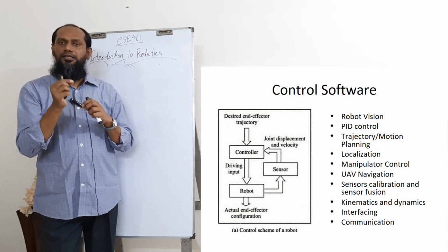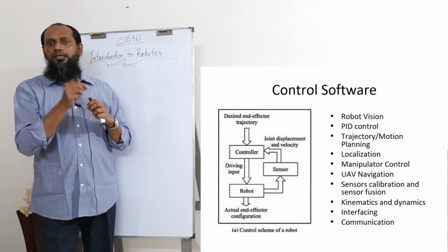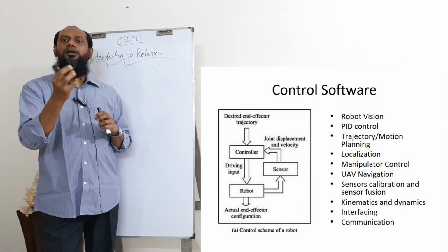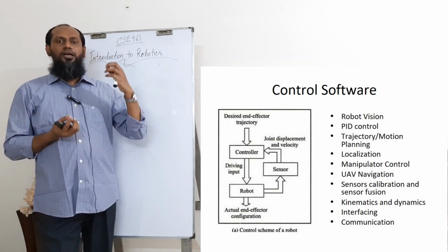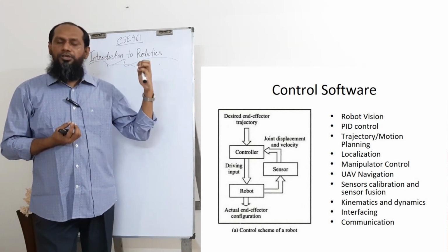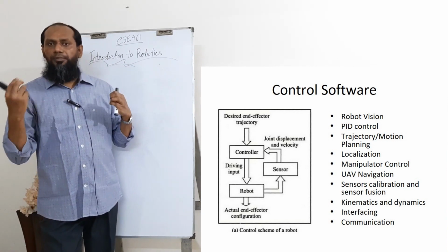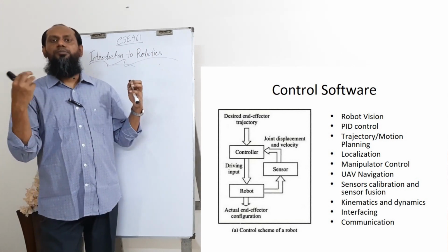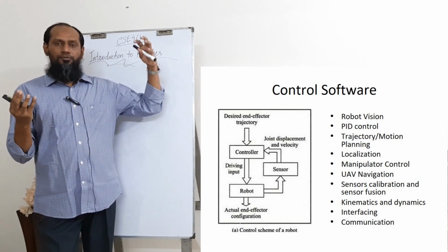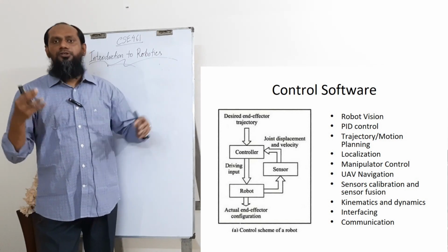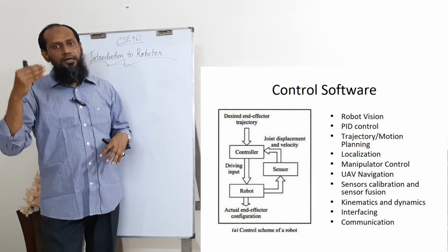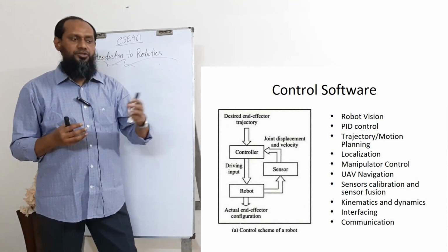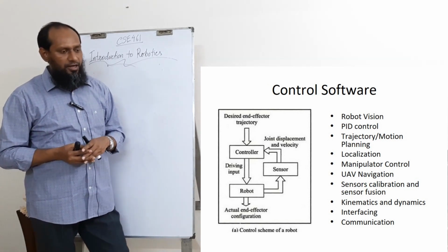Then an ADC is used for analog to digital conversion. Then our control system identifies, for which amount of light, what will be the number. That is the calibration. In the same way, for which sound level, what will be our number. So from analog values to digital values, we need to have some calibration. Calibration software is another very important software of the control system.